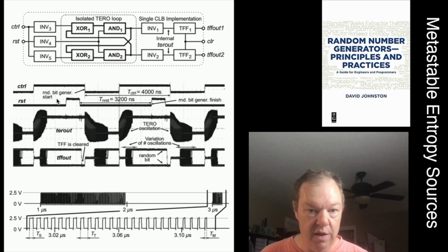And so here is the control input wire moving up, and you get a period of oscillation here. This is the voltage oscillating up and down until it ends up high. It finishes high, and then the control input wire goes low, and it starts oscillating again until it lands low. So it's like an RS flip-flop, but a really bad one that goes metastable and then resolves every time you invoke it.